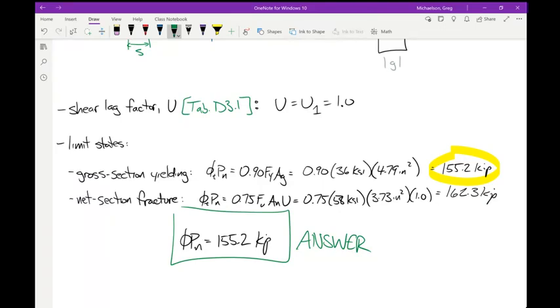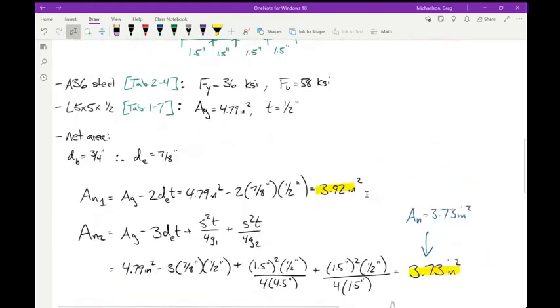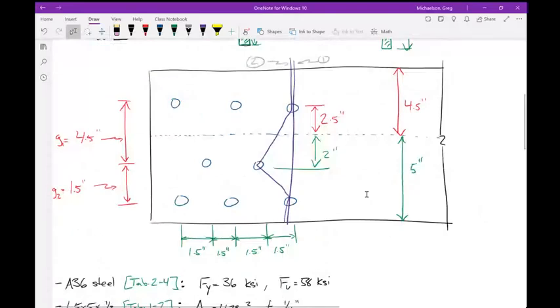Can you go over again how you knew exactly what path it was going to take instead of having to draw out all the different possibilities when we were talking about the fracture? You talking about this? I want to make sure I know what you're talking about. Yes. So in that case, whatever line you take has to go through both bolts, not just one, on the lead line.